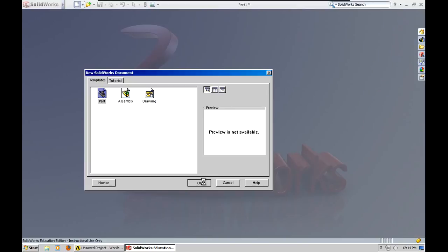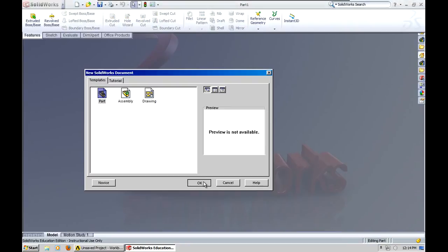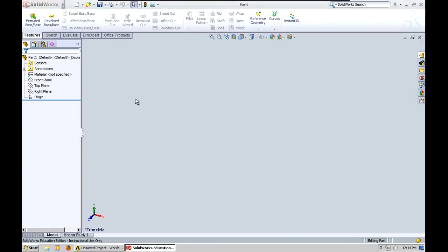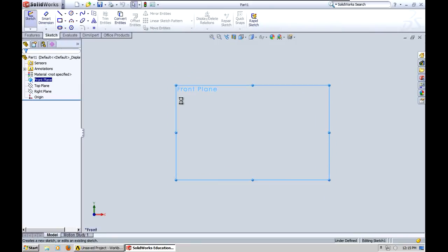I won't do it, but I'll show you where the command button is to fill it with fluid. You tell the program where the two caps are, like the inlet or exit, and there can be several of those if you want. Then you've got a solid and a fluid domain.